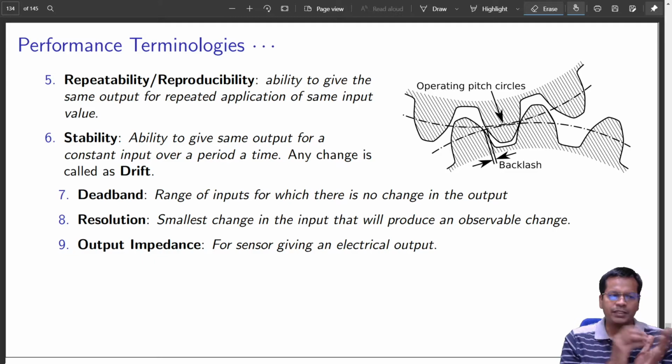Any equipment, if it is to be connected, let us say you have a speaker and that is an output speaker, it basically defines how much current it is going to take away from your system. If your USB is supplying a sensor and your sensor is of very low impedance, it will draw a lot of current from your USB, and then your PC may cease to work properly.